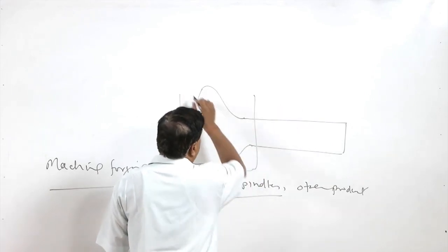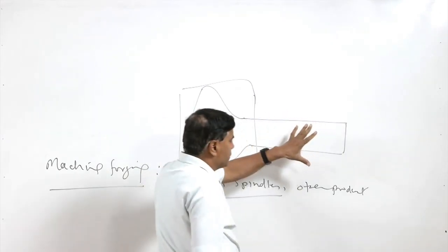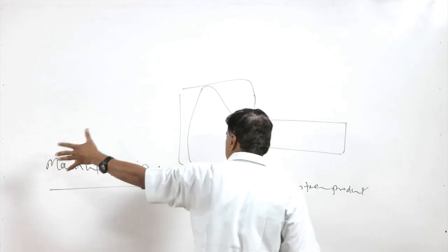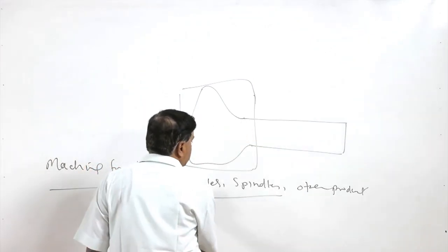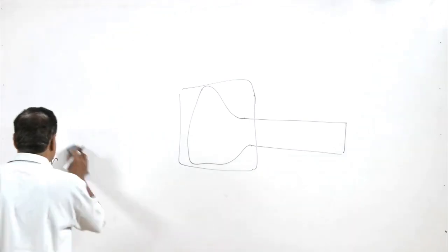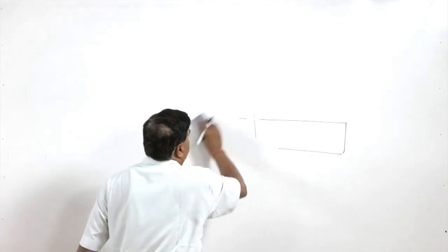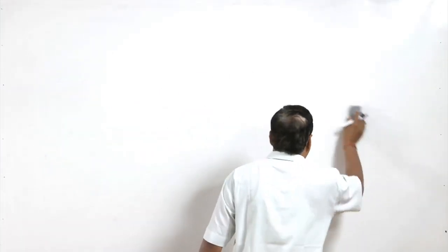This may be of different cross sections. For such cross sections, where one end is of smaller cross section and the other end is large, machine forging is normally used, and axles, spindles and heads of bolts are the common examples of machine forging products.